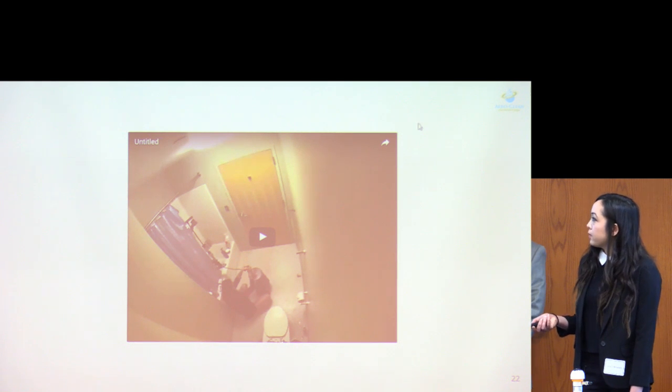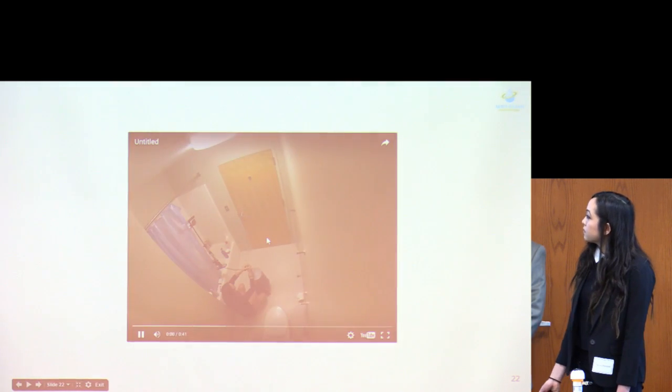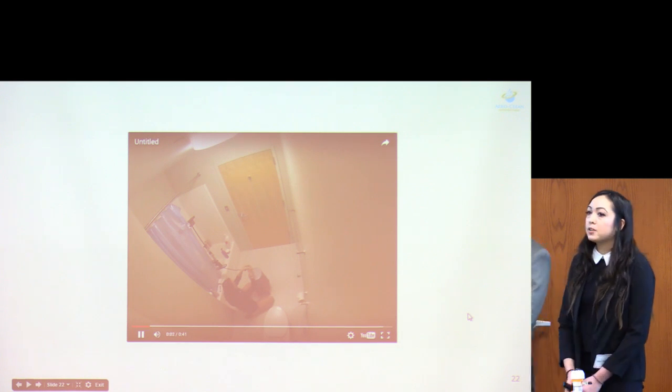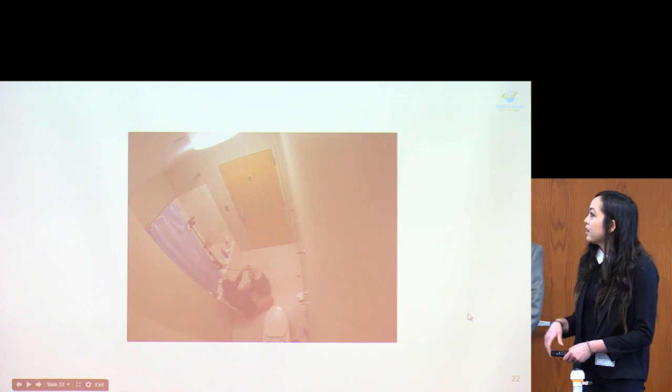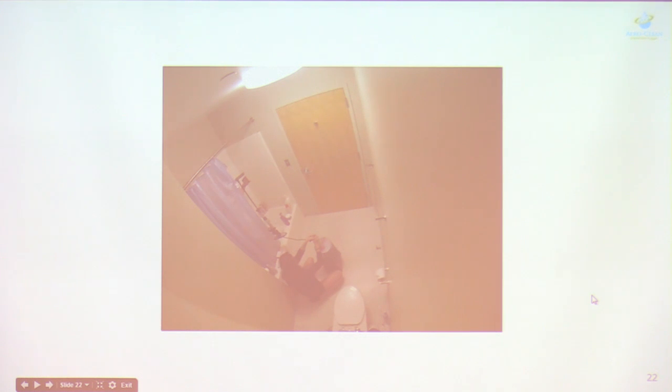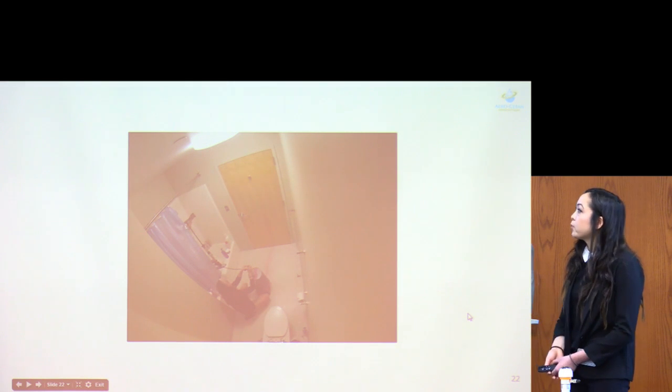And this is a video clip of our fogger test. It had to be held down manually because the adapter was printed a little too small so it wouldn't lock into place. So it's held manually throughout the test. You can see the solution's colored red, so you can see the spray pattern. I observed that the spray was coming out of all 4 nozzles, but it seems like it's more concentrated going toward the door. There was also a little bit of leakage because there was a small gap between the valve inlet and the cap, so there was a little bit of room for solution to escape.